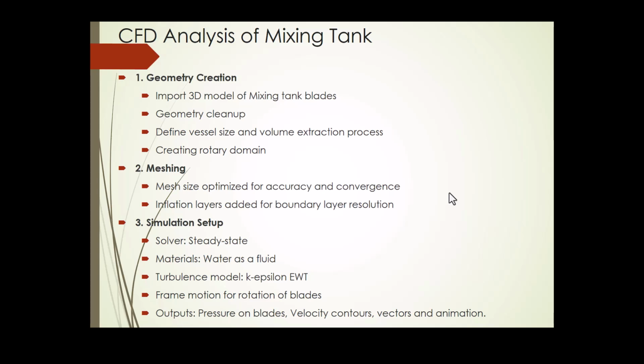The third step is the simulation setup. So we are going to solve the steady state problem. We'll be using water for the mixing purpose. And as a turbulence model, we will be using the K epsilon enhanced wall treatment model. Next step is to rotate the blades. So in order to rotate the blades, we'll be using frame motion. So I'll be teaching you how to use the frame motion.